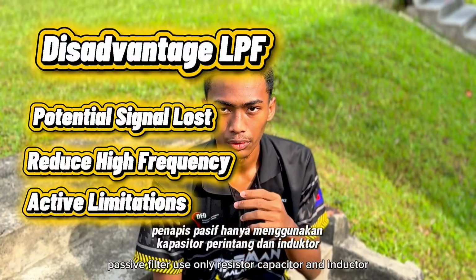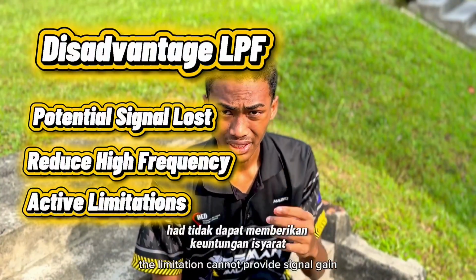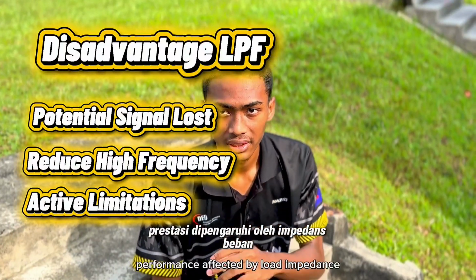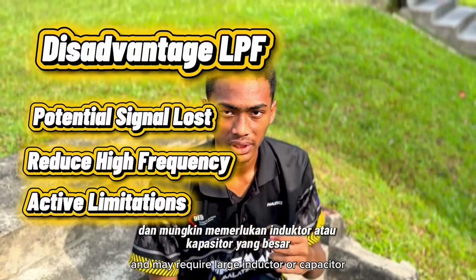Last one, passive limitation. Passive filters use only resistors, capacitors and inductors. The limitations: they cannot provide signal gain, no amplification, performance is affected by load impedance and may require large inductors or capacitors.